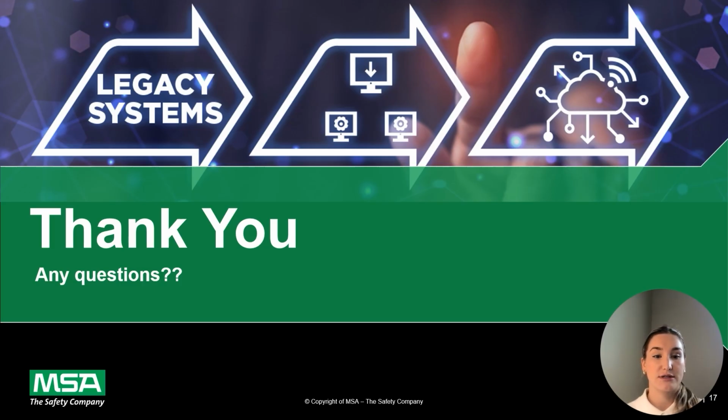The good news is a modern gateway can help here with built-in diagnostic features. Auto discovery, where you can automatically identify registers, reduces human error. Logging helps you pinpoint whether the issue is wiring, configuration, or network load. But yeah, troubleshooting is never very glamorous, but it's really important to have the right tools to help you figure out what the problem is.